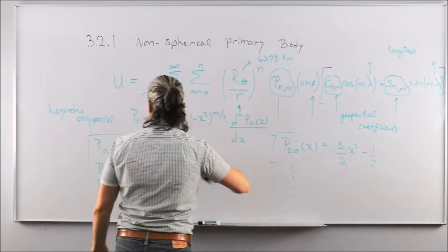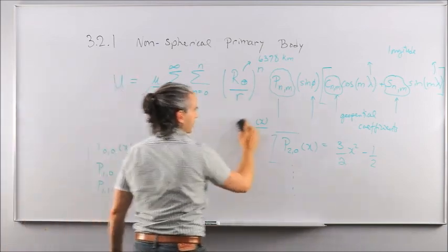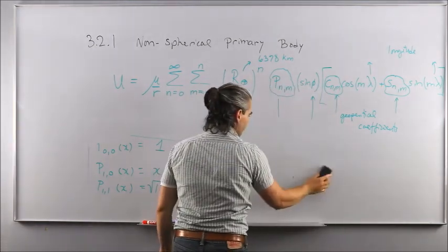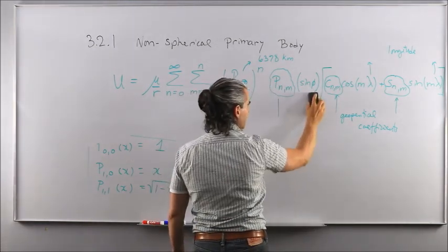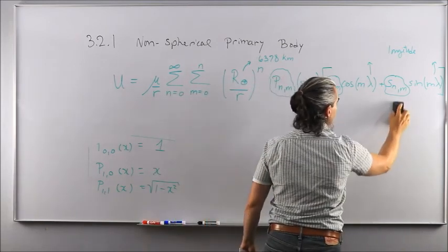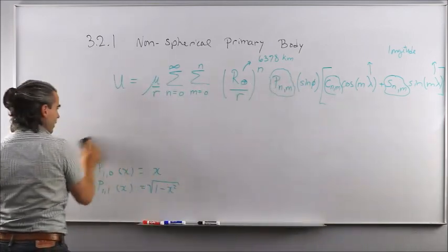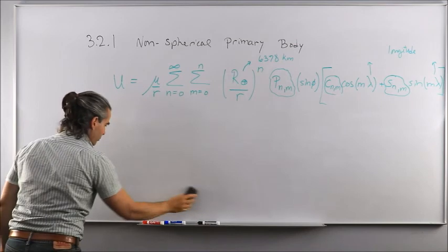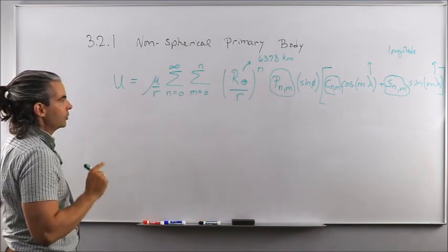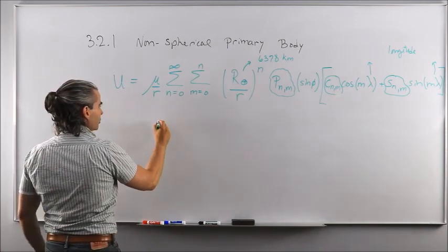Because, again, our objective here is not to get the most accurate geopotential function of the Earth that we can think of. We're going to leave this to folks at NASA and at the Canadian Space Agency and organizations like that. So here in the context of this course, all we'd like to know is the biggest gravitational contribution in terms of perturbing acceleration on our spacecraft. So to do so, let me first talk about the geopotential coefficients.